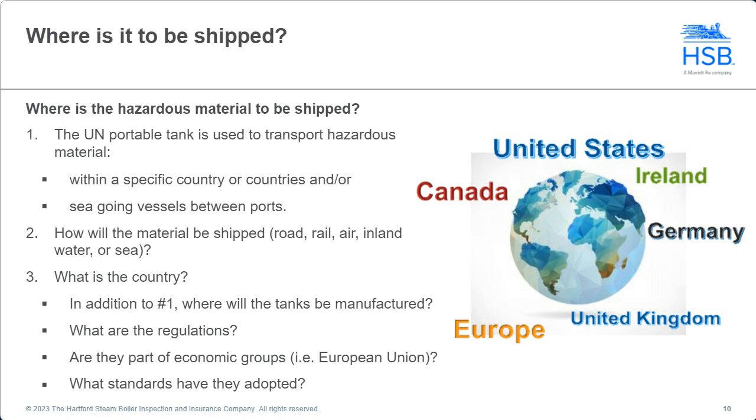However, if that portable tank also meets the requirements for a container under the Convention for Safe Containers, a longitudinal impact test is required, which has to be witnessed by an agency approved by Transport Canada. So those are some of the things that matter when you are manufacturing a tank: what country it's manufactured in, and where it is going to be used for transportation of hazardous material.